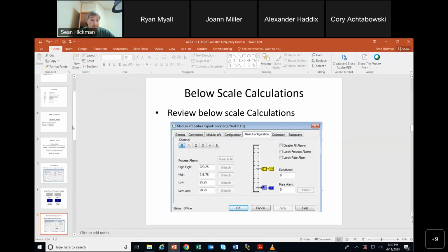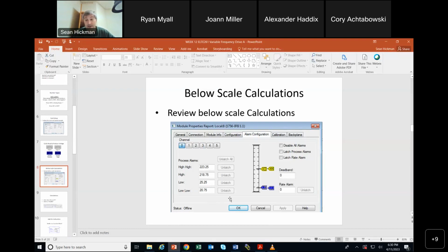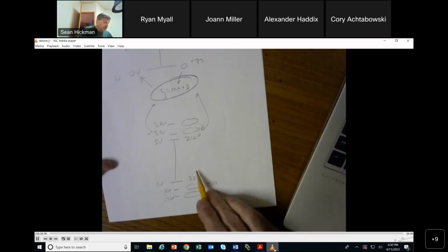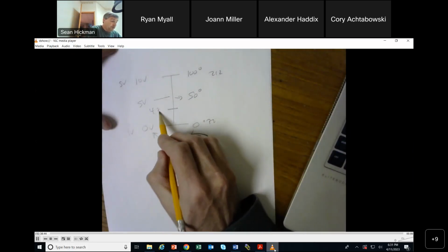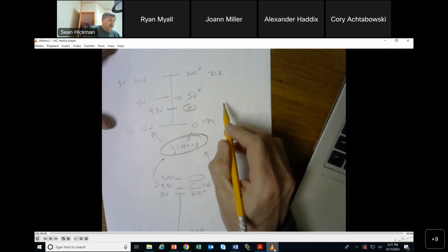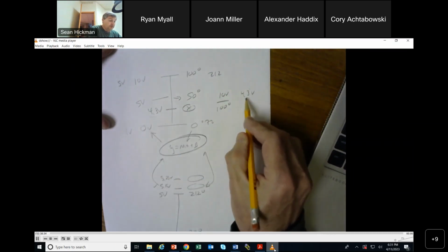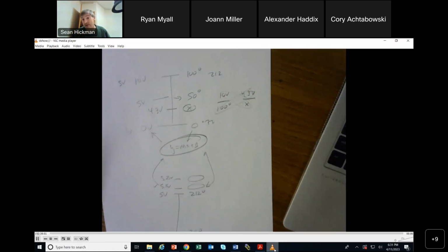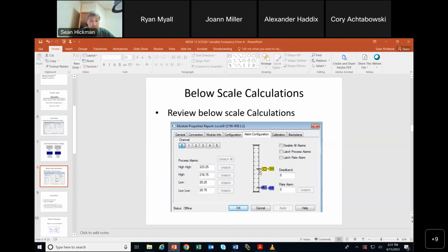All right. But once again, the card did it for you, and you had to do it yourself. And it was like, God, I don't like this math. Some of you like the math better than others, but because it was 1 and 5 and 32 and 212, you just couldn't cross multiply. Whereas here, if I gave you 0.43 volts to X, that's where you could say 10 volts is to 100 degrees as 4.3 volts is to X, and that's where you just cross multiplied and solved. Yeah, when it's all ratioed out equally, it works. But when things don't start at 0, that doesn't work. All right, and that's why we had to do the math there. So we went and we set those up.